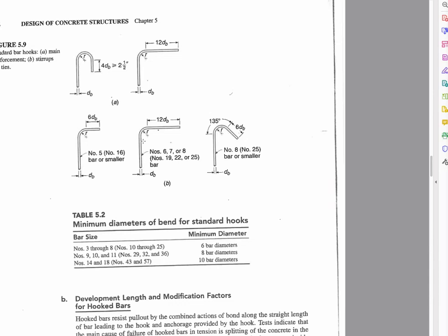And therefore, it needs some length in the concrete to do so. So we're going to define some minimum development lengths. And when we do that, you may find that the geometry of your pad of your footing simply doesn't permit there to be sufficient development length.